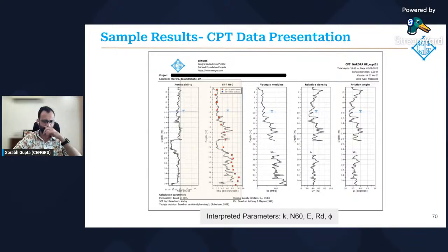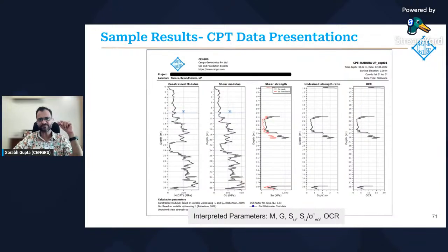It's such a good match. I think this is very reassuring to older geotechnical engineers who are more comfortable with SPT. This is a great source of reassurance for all of us that the CPT is telling us the same story as what a well-performed SPT investigation would tell. Now note here, I'm saying N60 because the N values have to be corrected for 60% energy transfer ratio.